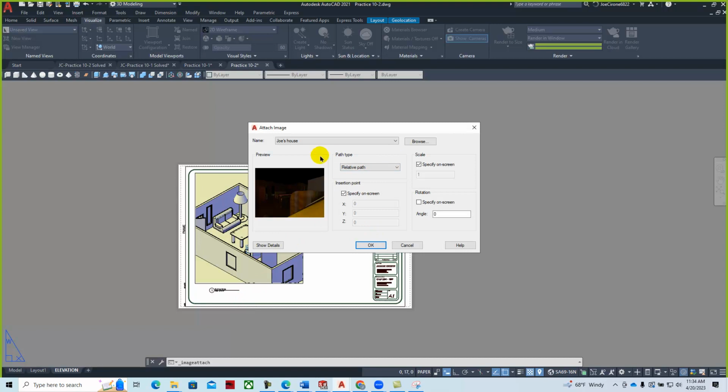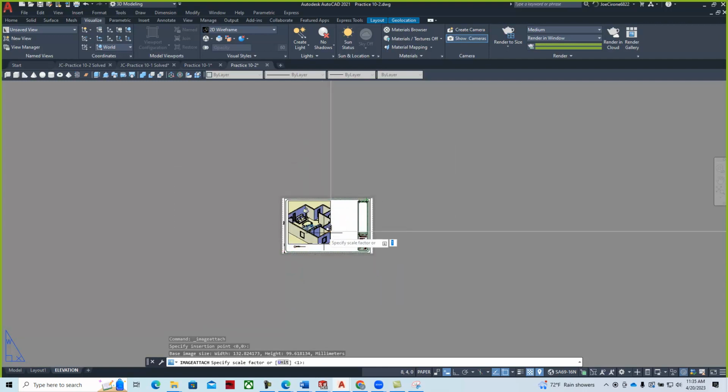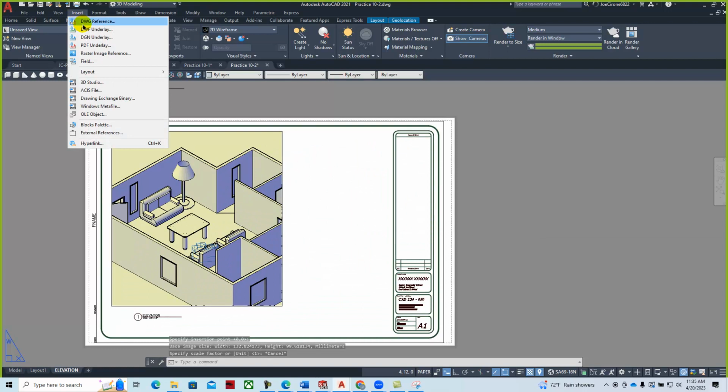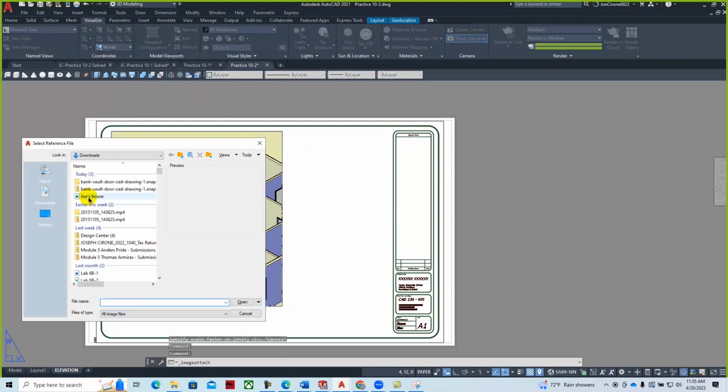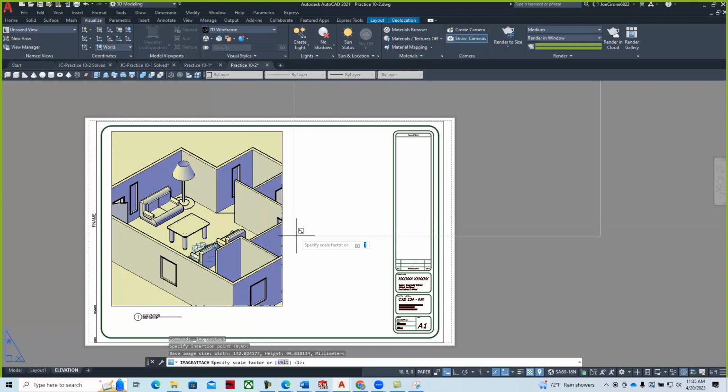And then it'll save that. You want to keep that file in the same place you save it. And so right now it's in downloads, but I would have been better off to put it in my CAD 136 directory, because what'll happen is you'll come back to the drawing later and look for the associativity of it. And so this is huge. Let's try that again without snapping to that point. Insert raster image, Joe's house, open, okay, and let's just go with 0.5.